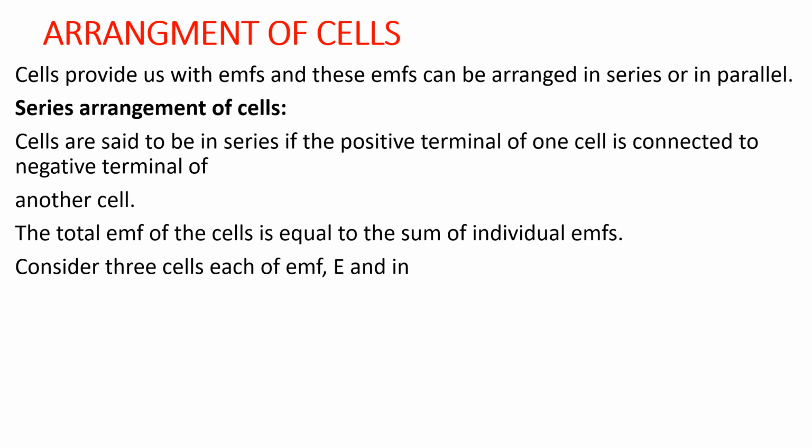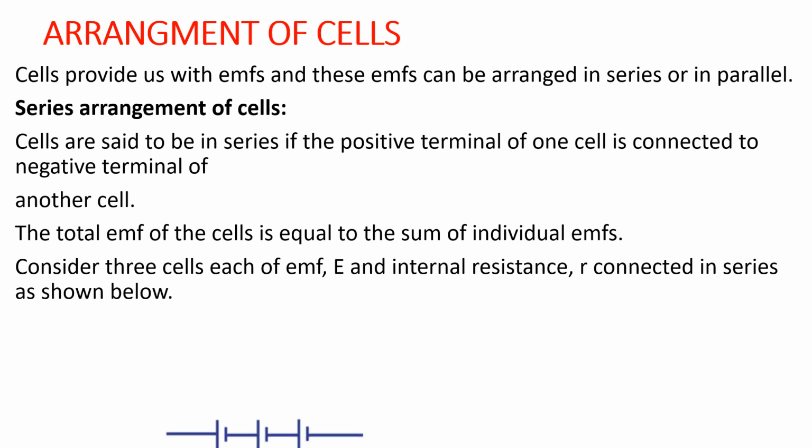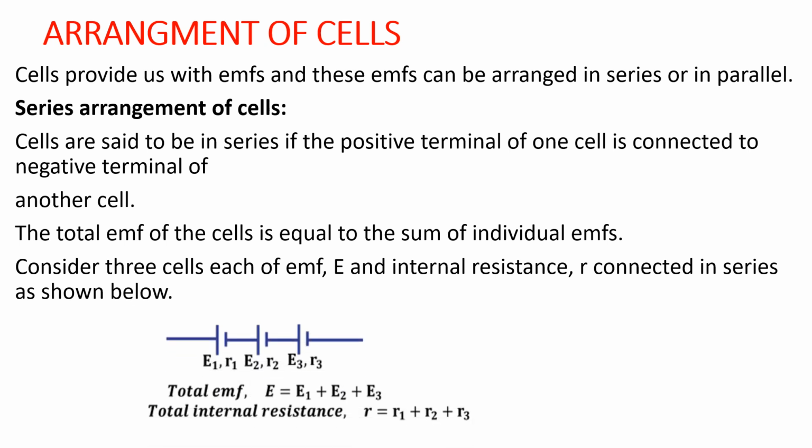When you consider 3 cells of EMF E and internal resistance r connected in series as shown, you realize the total EMF is adding them up, and since they are in series, we use the formula for effective resistance as the addition of the individual internal resistances. Parallel arrangement.